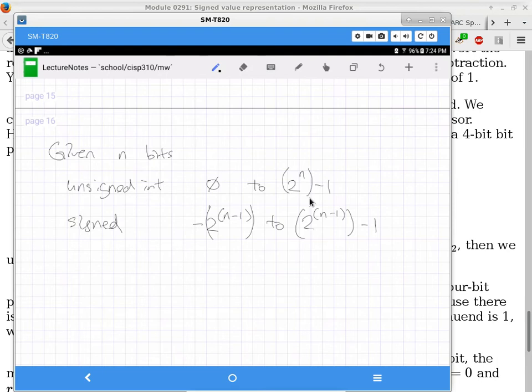As it turns out, an integer, if you just say int, is only 16 bits wide on that particular platform, but it is natively at least 32, if not 64 bits wide on a PC. So on a PC, an int is wide enough to handle all the values that the program needs to handle.